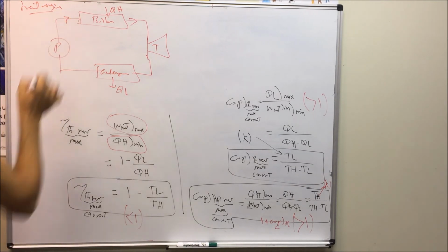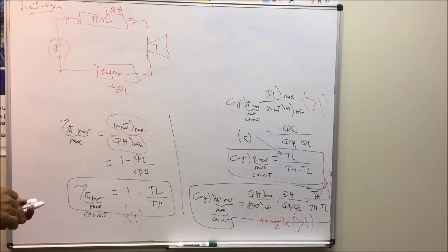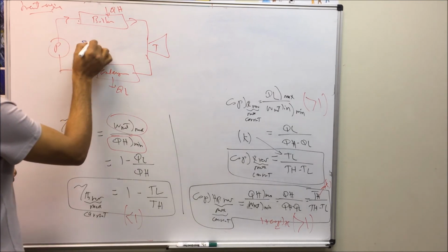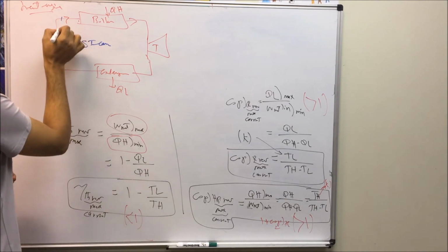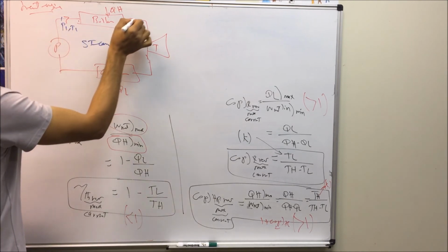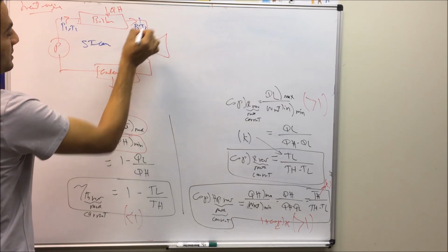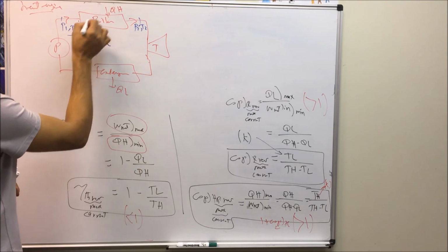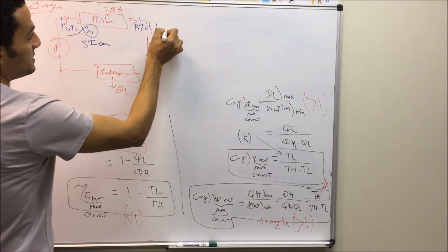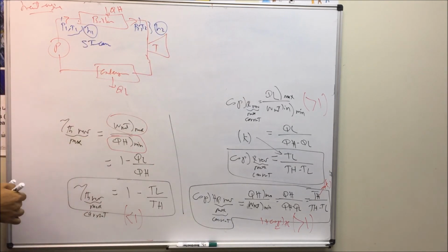In a steam power plant, the working fluid is steam. If he gives you the condition before the boiler, let's say P1, T1, and here P2 and T2 are given, then from a steam table we can calculate h1 and h2.